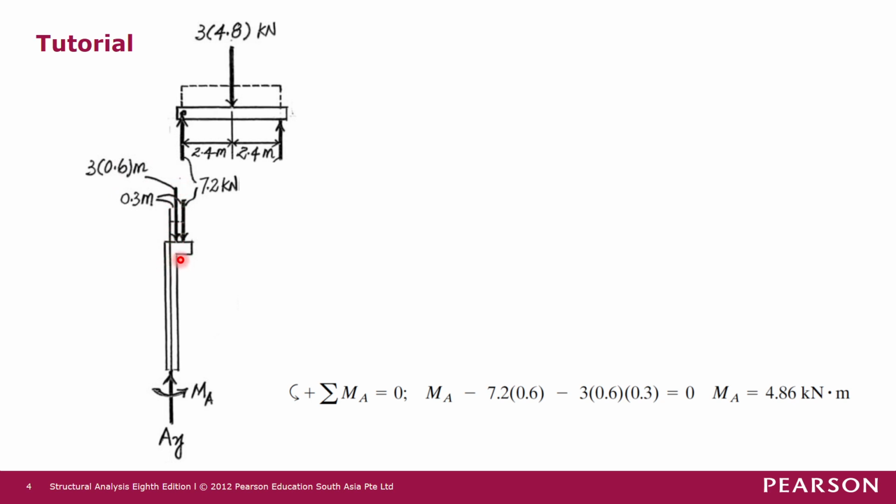The distance is half of the total length where the uniformly distributed load is acting, so it's 0.3 meter to this 1.8 kilonewton force.